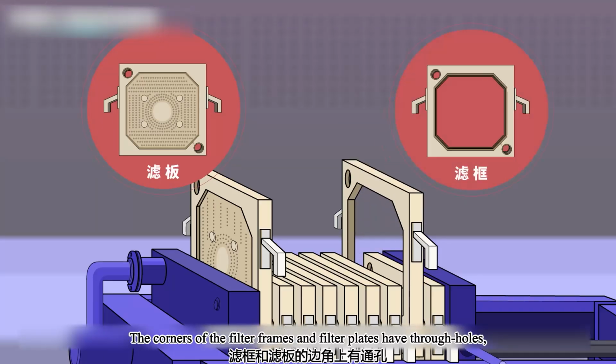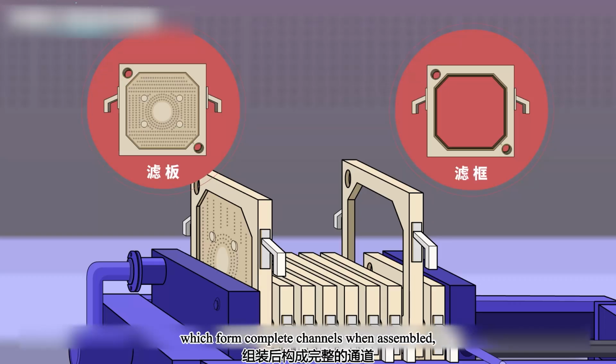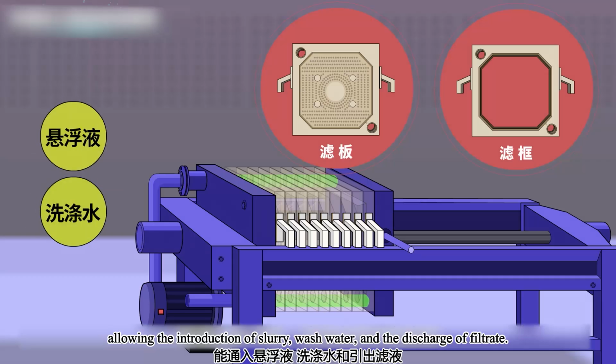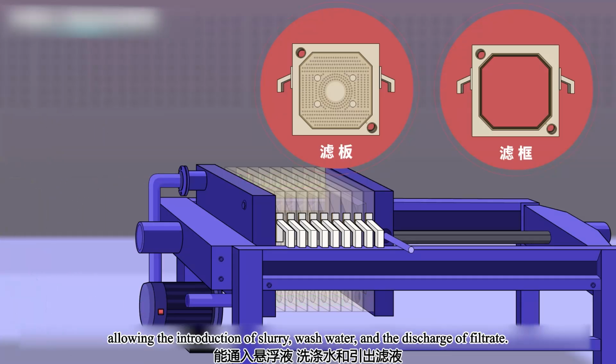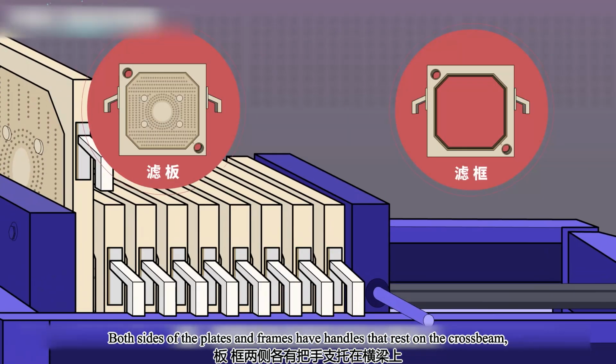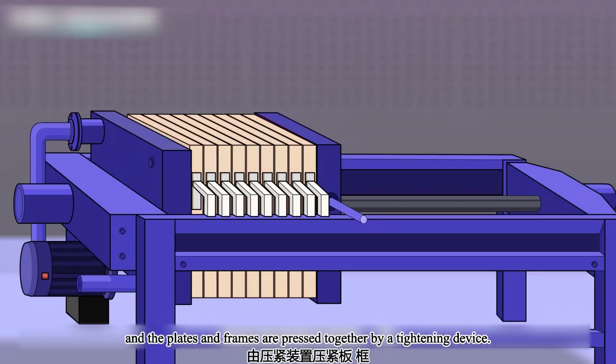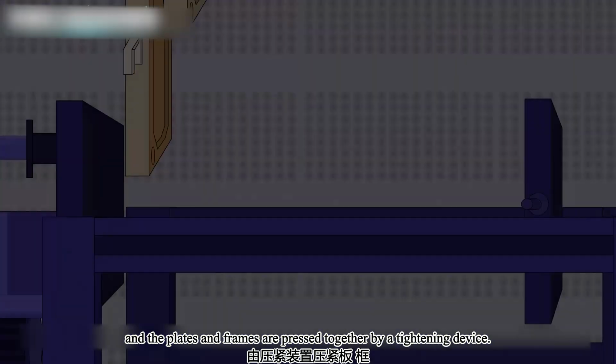The corners of the filter frames and filter plates have through holes, which form complete channels when assembled, allowing the introduction of slurry, wash water, and the discharge of filtrate. Both sides of the plates and frames have handles that rest on the crossbeam, and the plates and frames are pressed together by a tightening device.